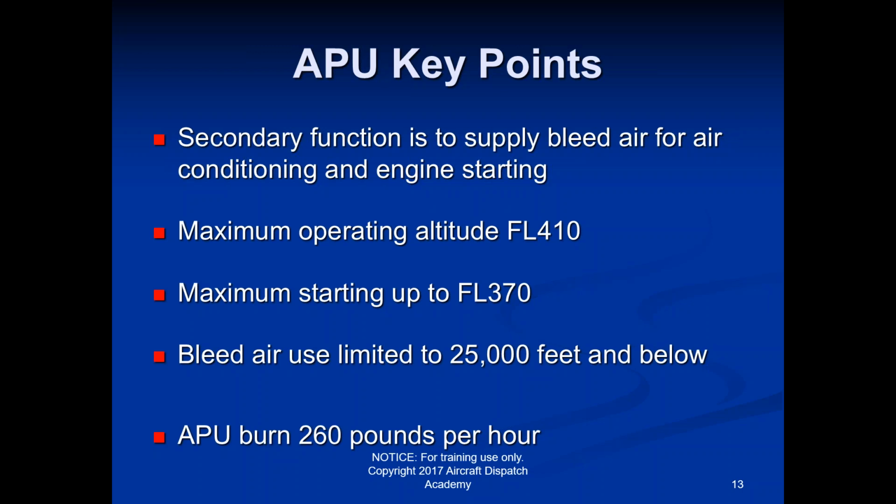Anyway, so they have those machines. They hook them up to the plane, and they just start blowing air in there, and that's the air they can redirect from the machine over to the engine to start it up. And then once they get one engine started, that's all they need, because once you start one engine, you can take the bleed air from that engine and start the other engine. So you just have to be able to start one engine.